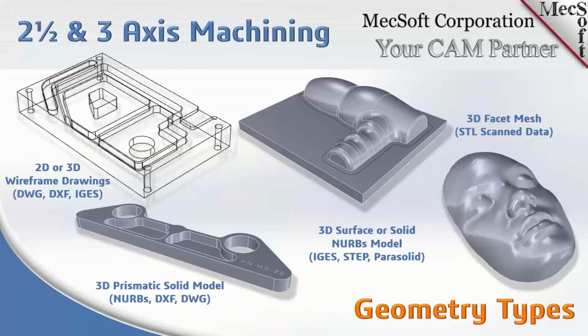Okay, let's talk a little bit about geometry. In our CAM products, you can program tool paths with just lines and curves. Like you may have a wireframe drawing. Typically, wireframe drawings are not used much anymore. But if you had just a 2D drawing, top view of a part that you needed to machine, you could use that in conjunction with 2.5 axis toolpath methods to machine your part.